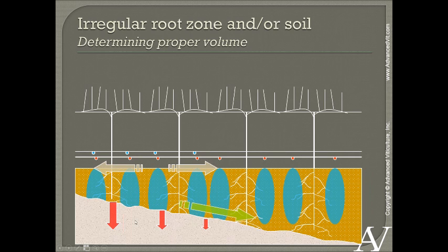You basically filled the sponge up, so it's going to go either below the root zone, the main root system. It can move either under subsurface if it's saturated, or more commonly on the surface. So we can get poor infiltration at the surface, and especially if there's slope to it, which there often is, it will run off. Usually down the vine row, often into the wheel track, which causes compaction problems. So that's a situation we definitely need to avoid.